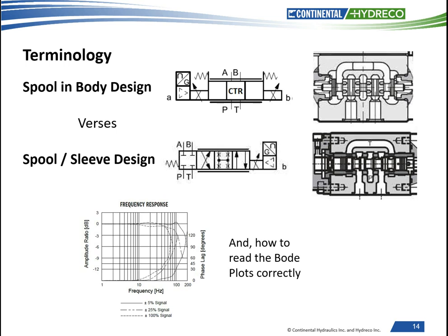Generically, with the J series the transition through this region is about 10 to 12 milliseconds of time. This step tends to drive high-speed motion controllers a little crazy. They don't like that step. The K series, though, with the improved electronics, going through this transitional region is about 4 milliseconds, typically fast enough that high-speed controllers can deal with it.